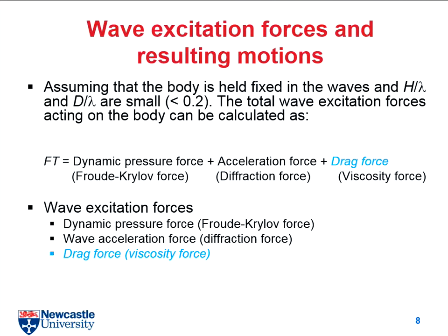Okay? And actually this page is from Professor Longbin, and I think probably it was from 10 years ago. So you may have some very confusing names for different terms. So after I give you this page, you can just ignore them. We just need to know that when you do the calculation for force or for acceleration, we use a different mass: the real mass of your structure and the added mass, and you can estimate the coefficient from the table, okay? But again, if you apply different rules, you may have different coefficients.